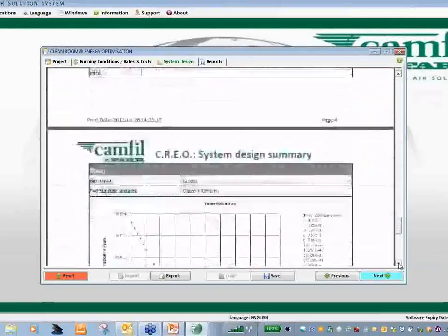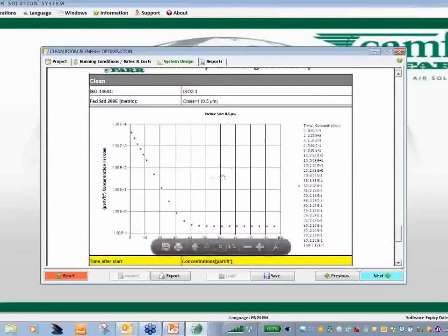This is the actual HEPA filter we selected, and I think this is an interesting report, one I showed you earlier. In this example, I think we've nothing in the room there, so it's an ISO 2.3 room, and then there's that steady state condition, which is around the 60 minutes or so, 40 minutes in this case, it starts to bottom out.